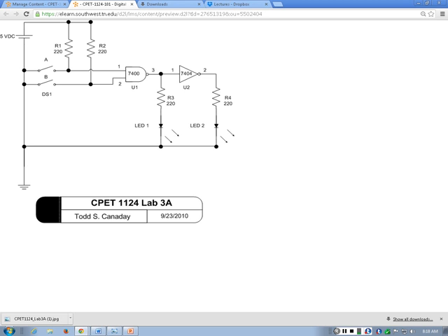Do you see this 1, 2, 3, 1, 2? These are basically the pin numbers. So before you start working with that, you will have to write those pin numbers, because once you have the pin numbers, you exactly know what to do. For example, you know that from pin number 3 of 7400, you have to run a wire up to pin number 1 of 7404. Do you see it? This line.